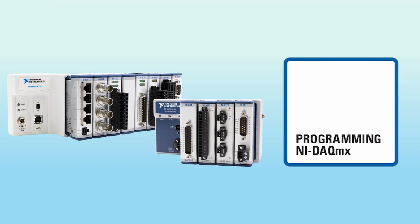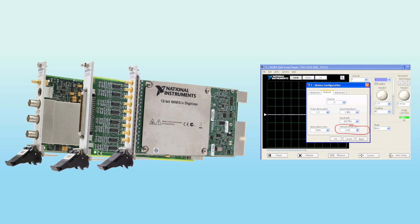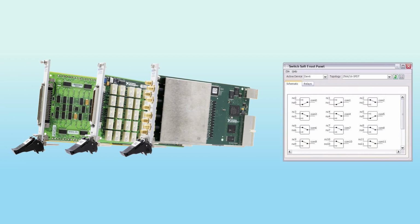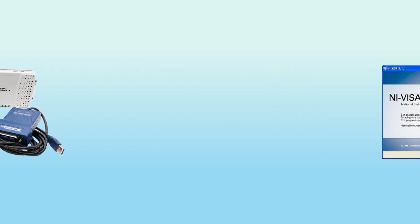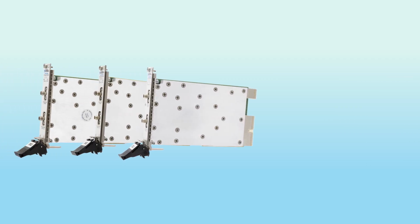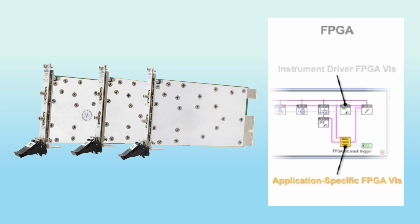For example, most multifunction DAQ devices, CompactDAQ chassis, and C-series modules use NI-DAQmx. Oscilloscopes and digitizers typically use NI-Scope. Digital multimeters use NI-DMM. Switch modules use NI-Switch. Serial and GPIB communication often rely on NI-VISA, and automotive network interfaces may require NI-XNET. If your hardware is RF-focused, FPGA-based, or part of a specialized platform, it may require a more specific driver or toolkit. That's why checking the exact model number is so important.